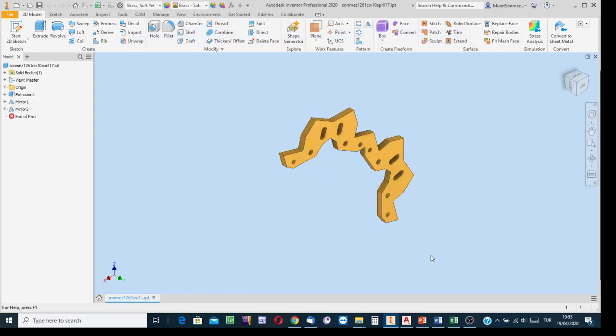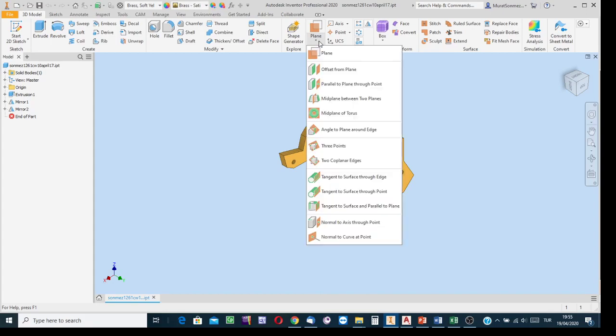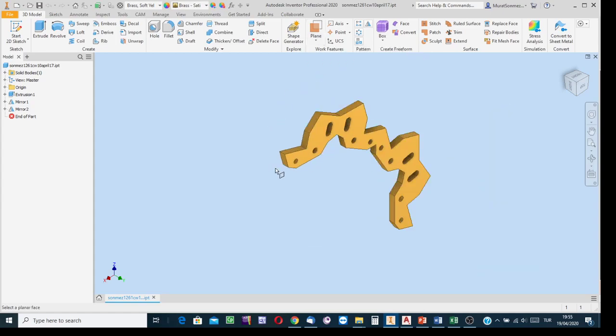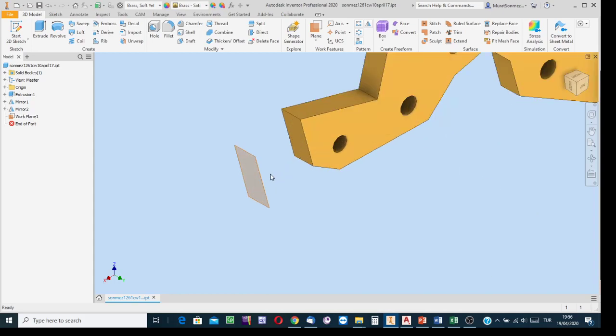And then, another classwork here, say that the mirror copy of the existing one is to be created not about its surface, but about a work plane. Select this option, offset from plane, and then indicate this surface as the reference, and then have such a work plane, how many units away, into this box write, say for instance 50 units away. Here is the work plane.